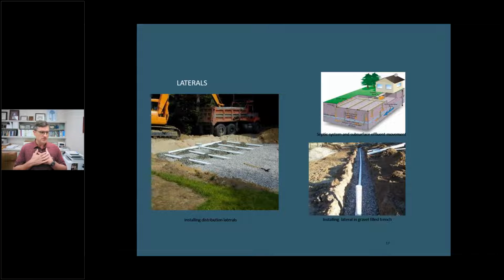Now again, us as owners and operators of these, we need to make sure that what we're putting into the system is going to help it as well, because again, as you heard me say, human waste, toilet paper, and appropriate pumping. We should be able to do that because most people try to get these built so that you have adequate treatment and then adequate discharge or dispersal into absorption into the soil. And with these gravel fields, you're creating that porous environment where it can be absorbed into the soil.